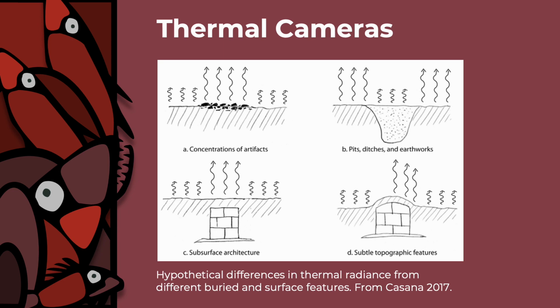At night, as the air cools, the ground surface and the features within it release heat. This will happen at different rates over different areas depending on thermal inertia, emissivity, and volumetric heat capacity of the soil and features. You may have noticed this phenomenon when walking from a grassed area to cross an asphalt road at the end of a hot day. You will still feel the heat coming off the road, even though the temperature has dropped. A thermal camera detects these differences.